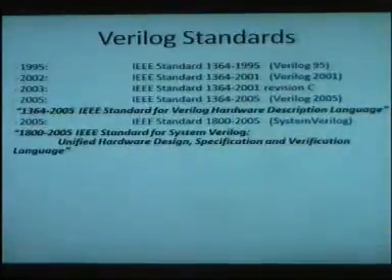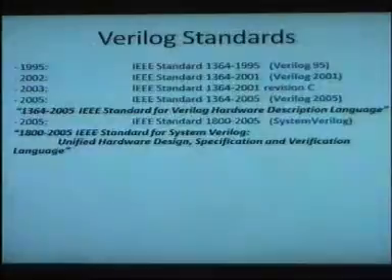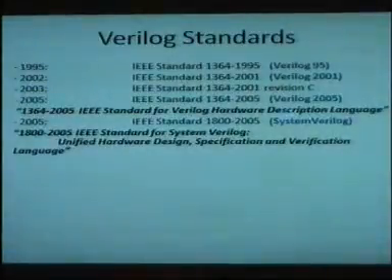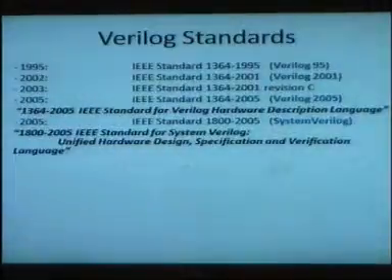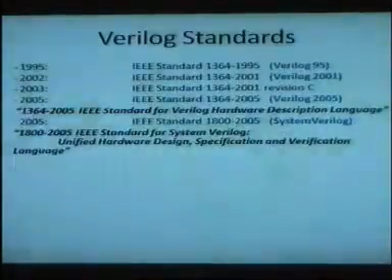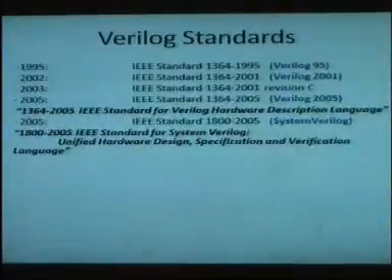So what you can do now is design your device in Verilog and your test vectors in System Verilog. Those of you who are good in programming languages, System Verilog offers you classes, inheritance, and all the concepts of object-oriented programming, and even more than that, the coverage, the way you can steer your test vectors, bias them in one direction, bias them in another direction, randomize them. So they added all the power of all those tools into System Verilog.